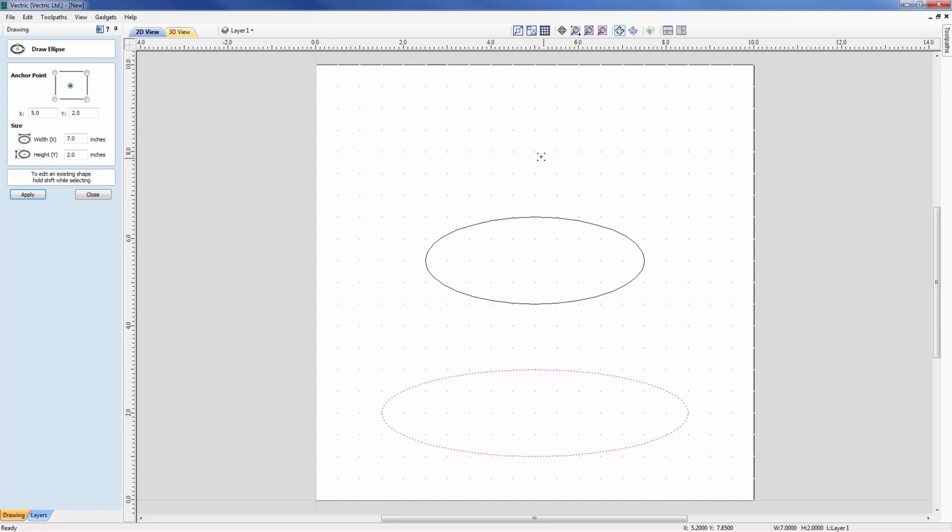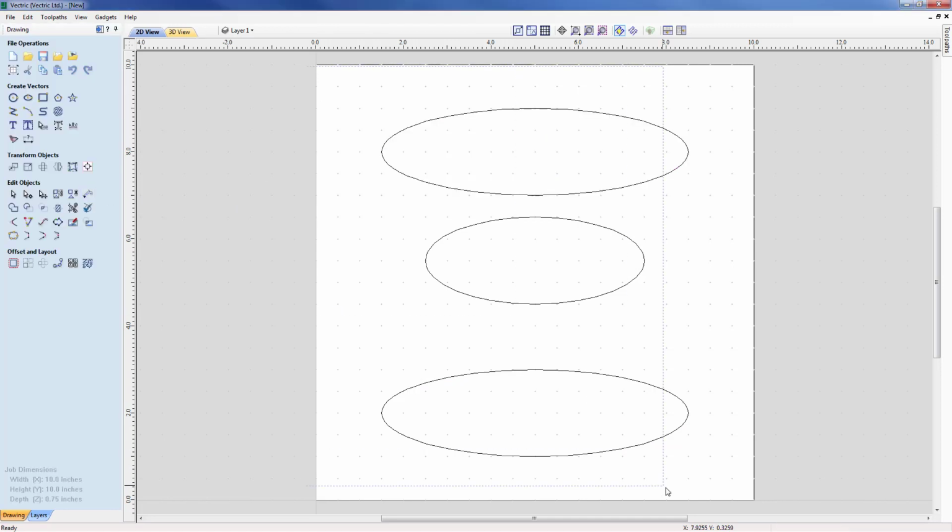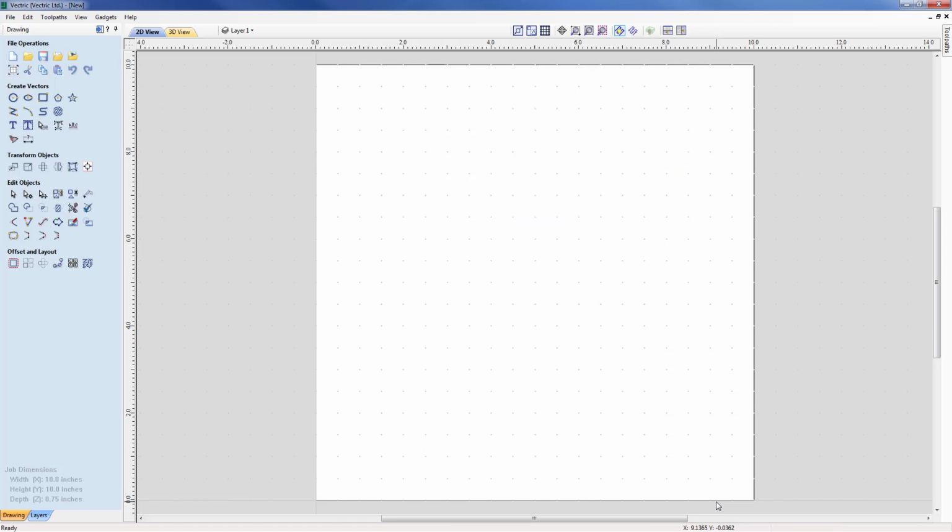And similarly, if I want to do the same by specifying the X distance, I can stretch this up now, so I know that I'm going to need it to be 2 in Y, but I need my width to be 7 in X. So I just type 7x. As you can see, I have a width of 7 and a height of 2. Okay, so moving away from ellipses, let's close that form down and then just delete out those vectors, and we're going to start looking at rectangles.